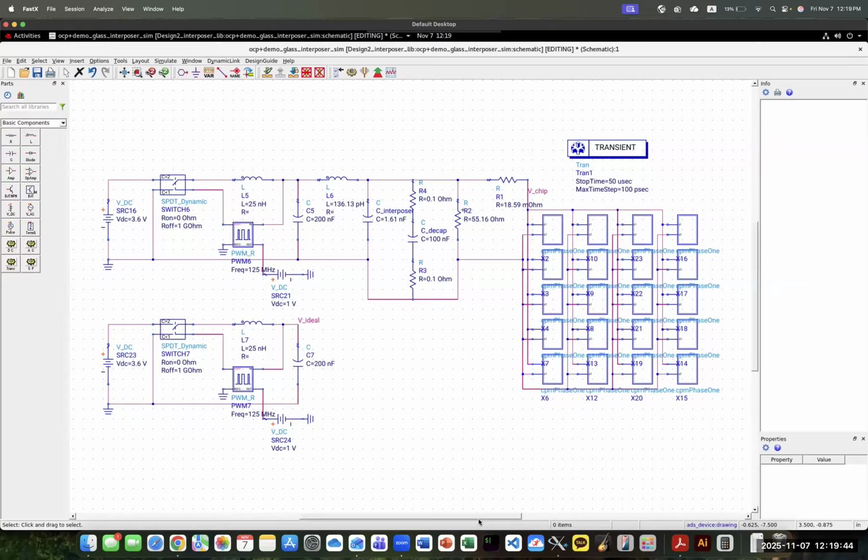We also talked about upgrading the CPM model a little bit, in the sense that this one is a steady state transient, meaning continuous activity at the same levels. It will probably be a good idea to look at changes in activity and see what happens to the PDN. That was one upgrade of the CPM models that we'll need to do.